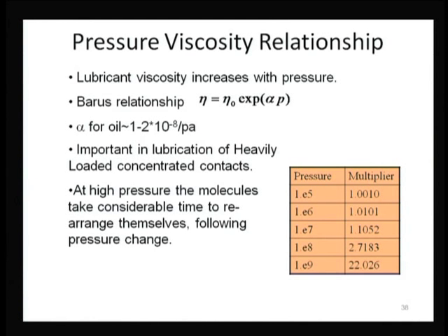Contact pressure can reach even 3 gigapascal, 4 gigapascal because of very high loading. And it is interesting to note that most of the load is shared by the liquid in this situation. So, what we say is that this kind of effect is important whenever there are heavily loaded concentrated contacts.